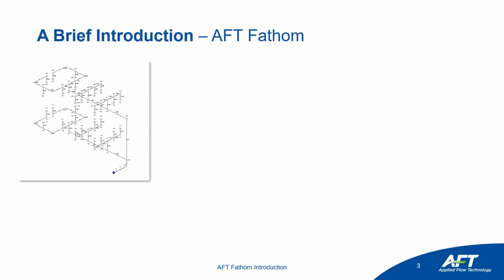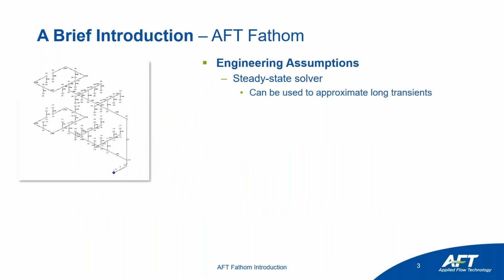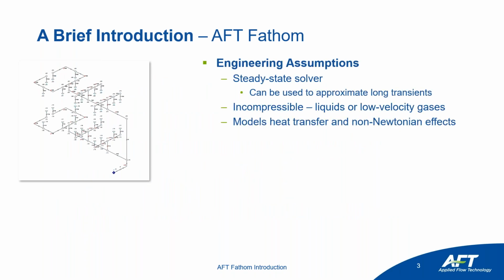So, a brief introduction to AFT Fathom. Some of the engineering assumptions we're dealing with: it's a steady state solver. So we're not looking at mass accumulation. Mass into the system should equal mass out of the system. If there's heat transfer in the system, again, it's a steady state representation of the model. We can use this steady state solver to approximate some long transients. We do that with the XTS module, which we'll touch on later in the presentation.